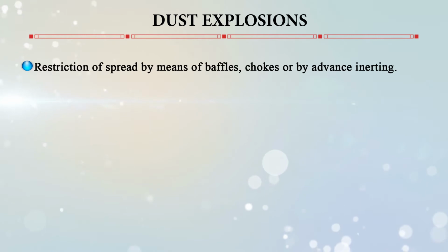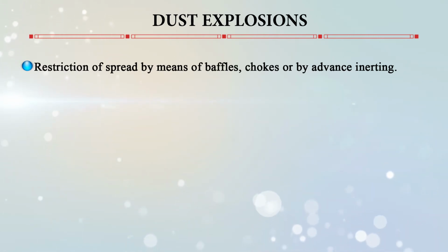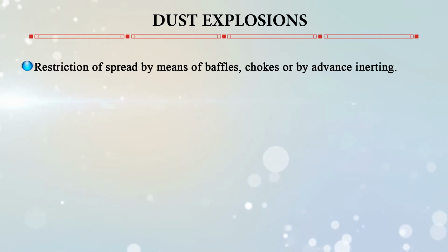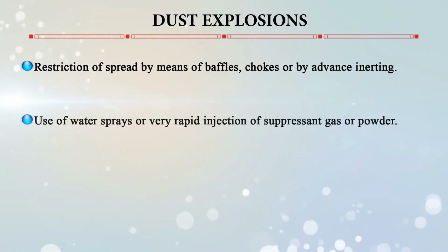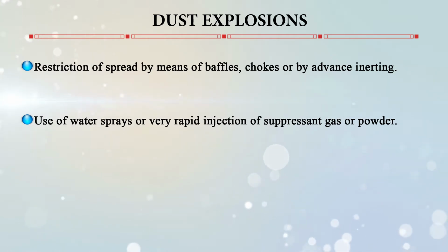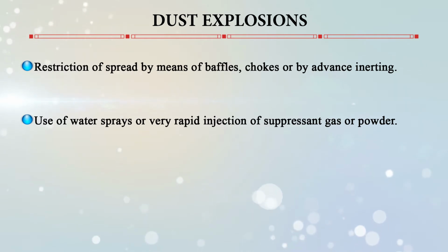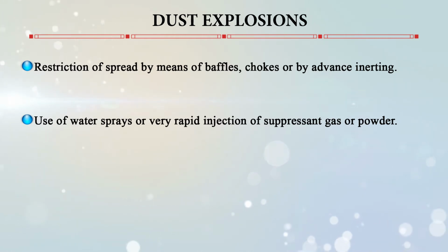Restriction of spread can be achieved by means of chokes or by advanced inerting. Use of water sprays is also one of the important mitigation measures, or we can use very rapid injection of suppressant gas or powder.